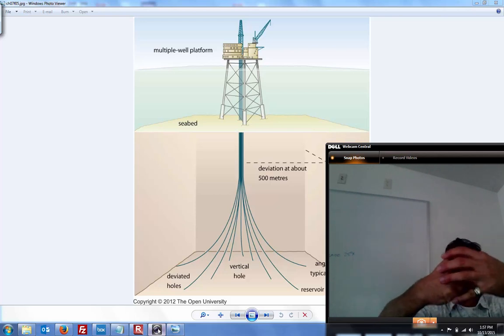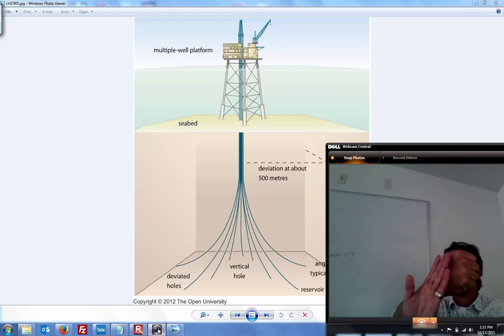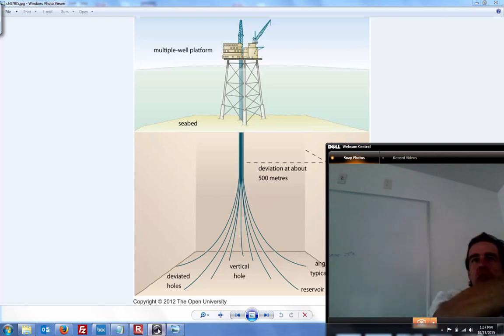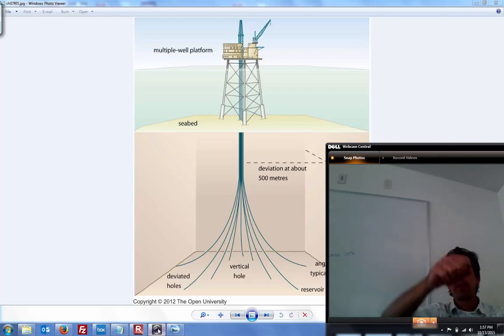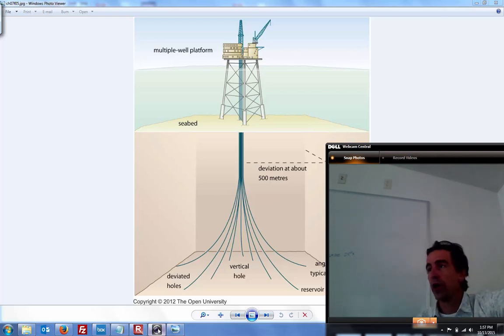So the drill head was sort of off to the left here, and there was a shoe or a pad on the right, which would basically act like a skid plate. So the thing was always going to go in some direction, but the operator could allow that drill head to go up or down, right or left. He's got a sensor on the other end that tells him exactly where that thing is underground. So you can see now, just expanding that to a larger scale, there's your directional drilling. It's like, oh gosh, how does this thing bend?